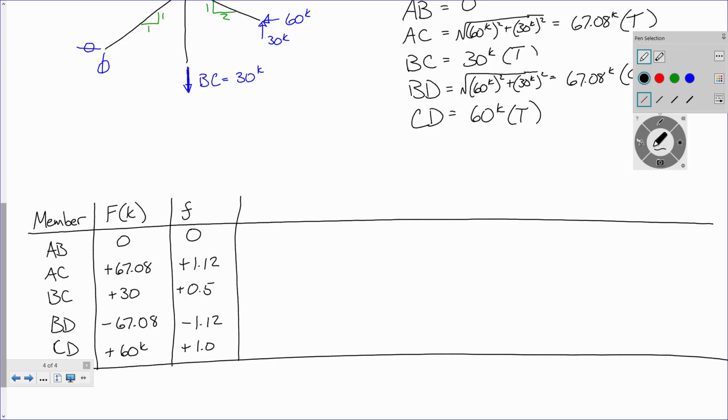Now, here's another caveat to doing deflection calculations. Deflection calculations with units can get messy. What are the units asking for in the problem? It's asking for deflection, and what does it express them in? Inches. If I want to calculate deflections, I have to have delta equals the sum of F, big FL over AE.